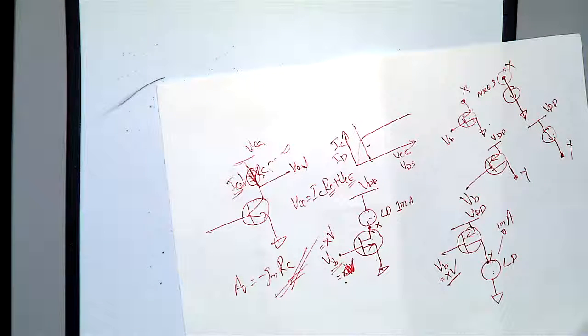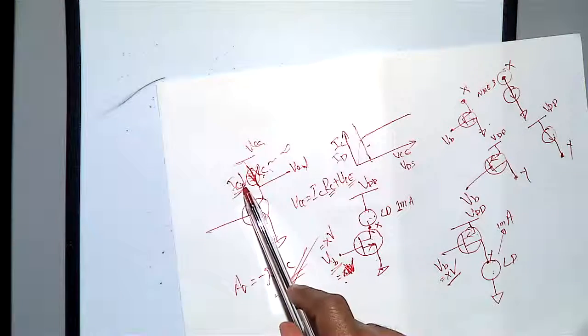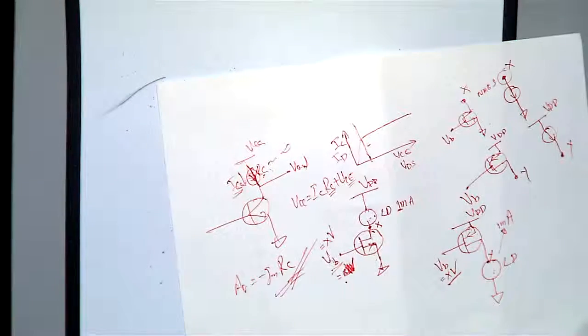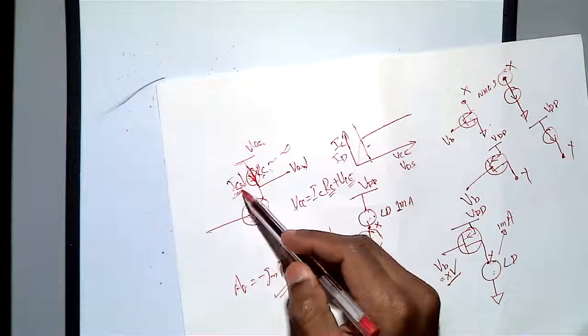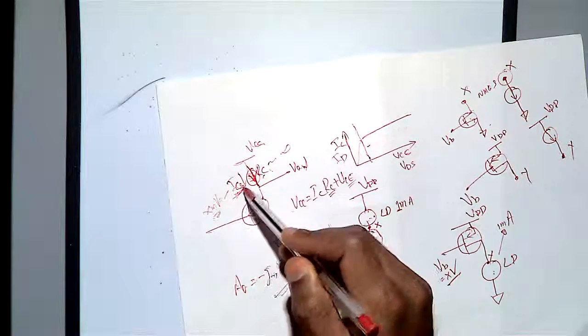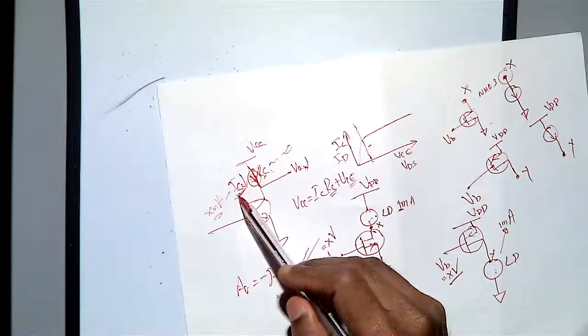The advantage of a current source is not only getting a very high impedance, but you can also keep the current constant. If you use a current source and keep this current IC at some value X milliamps, it will keep that X milliamps as your DC bias current.